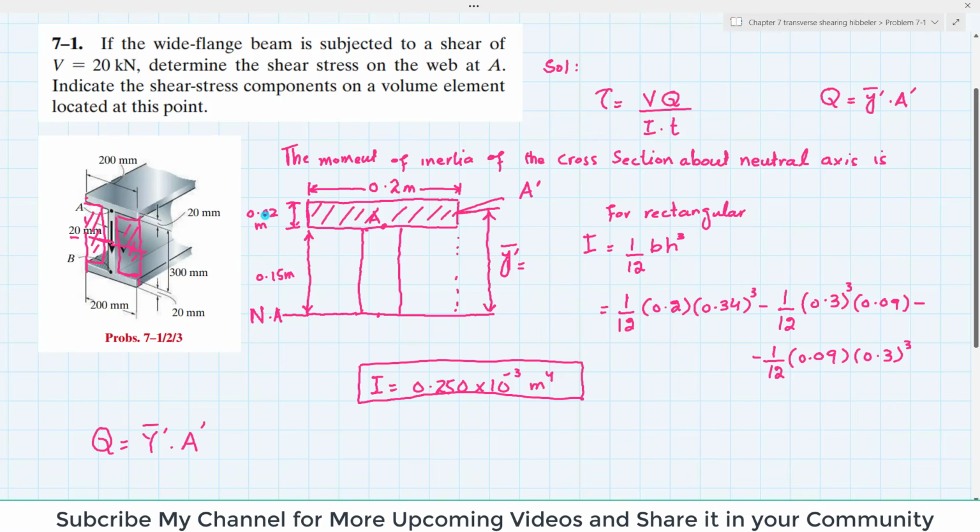Okay, so what is the value of this y dash bar? If you divide 0.02 by 2, you will get this half distance, which is equal to 0.01, and this is 0.15. So it will be equal to 0.16. So y dash is equal to 0.16 meter. And what is A dash? A dash is the area of this cross section, which is 0.2 into 0.02. So we will calculate this Q.